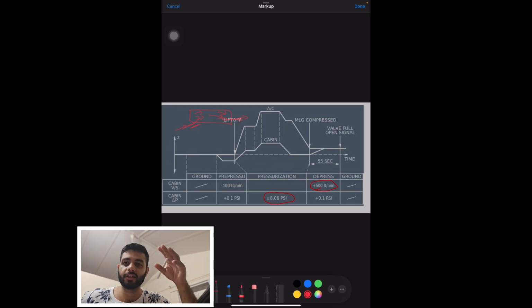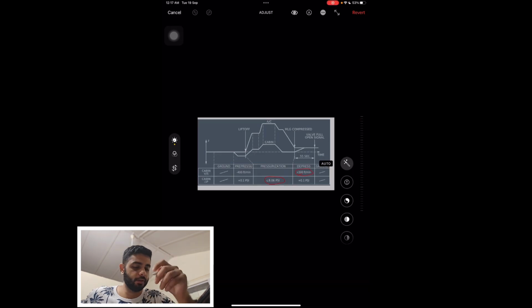Okay, if I press the ditching push button, that valve is not going to open. Now another issue with the ditching push button is, if I'm on ground and I've pushed the ditching push button and the low pressure ground connection is kept in for the AC unit, then it'll keep on pressurizing the aircraft. Then the aircraft gets pressurized immediately. Okay, so you have to be careful of that.